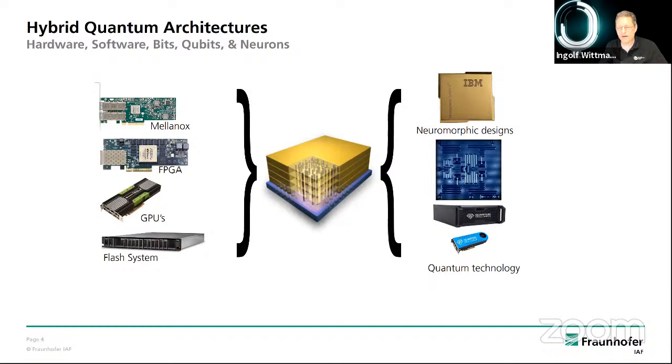When we are talking about energy consumption, for example, the synapse chip runs with 1 million neurons, having roughly 256 million programmable synapses, and there's no clock, which is quite interesting. You can run 46 billion synaptic operations per second, and the interesting part is that this is done with 70 milliwatts. So this is really fitting within mobile environments.